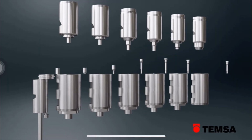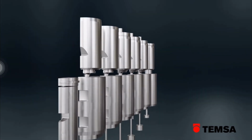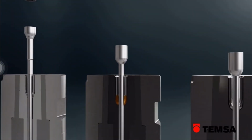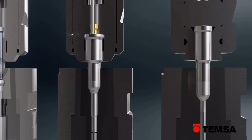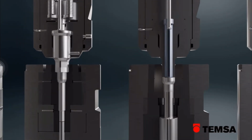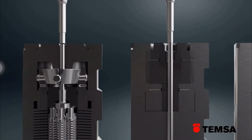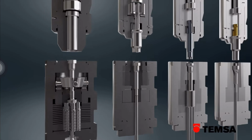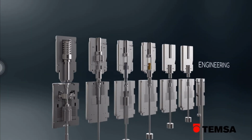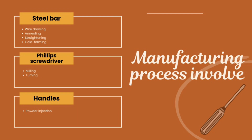Next, the wire is straightened by a string forge and then transferred to a cold forming press, which cuts the wire to the appropriate length and forms the tip of the screwdriver and the wings that will fit into the handle. The cold forming press cuts the wire.